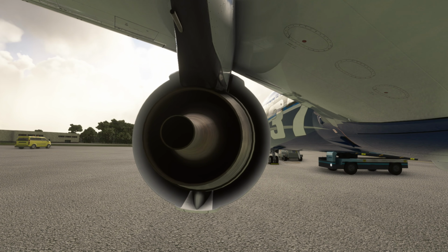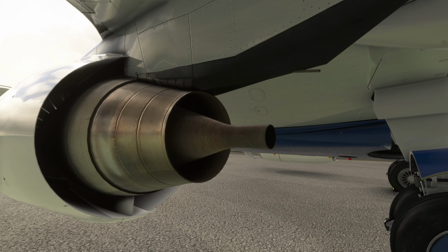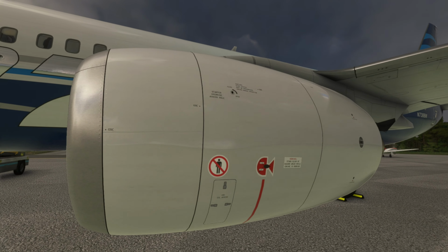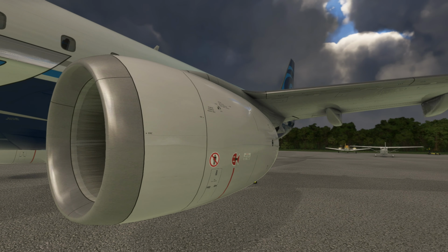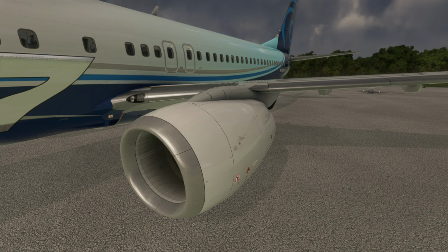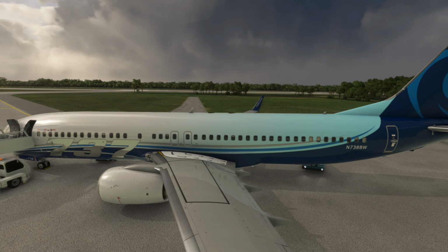You can see the core of the engine as well as the bypass portion of the engine thrusting aft to allow forward movement. This will redirect a lot of that airflow forward and down, allowing the engine thrust to start to affect deceleration of the aircraft. And again, that's something that is enabled only on the ground. Those thrust reversers obviously are actuated via hydraulic pressure.